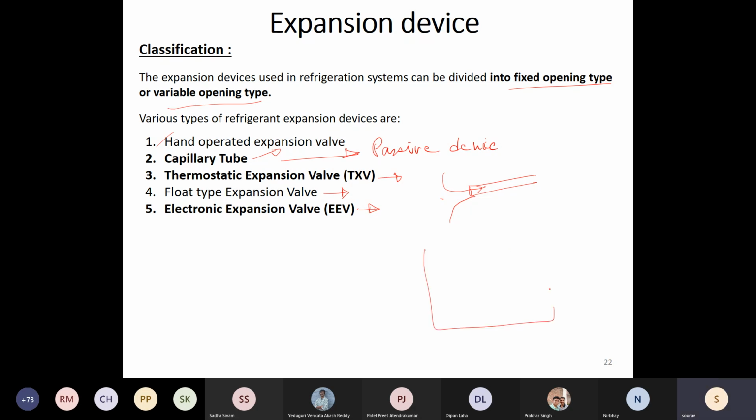So there is a floating ball, okay, which is connected by a rod to the actual valve, and this is connected to your overhead tank, and water just simply falls from the bottom side and it fills up, and there is just a small plate which opens and closes, this one.